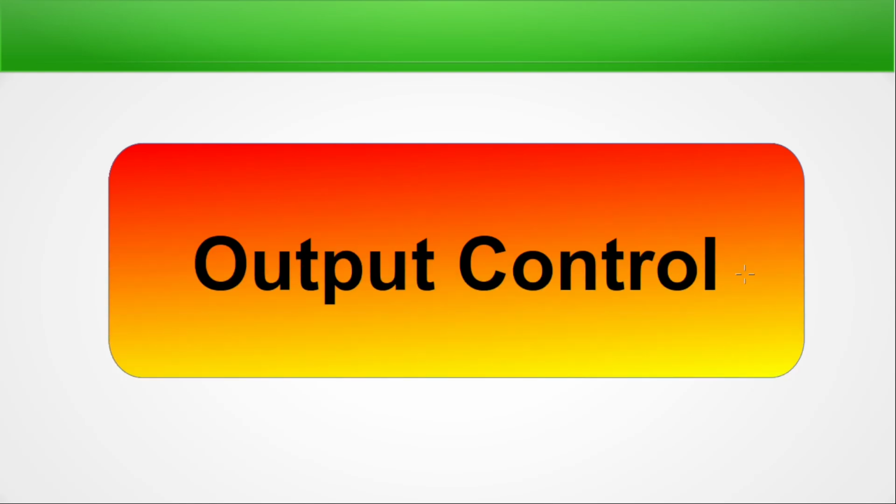Today's episode is focused on the output control of the SPICE. So this is the philosophy that we are going to cover in the entire episode today. So let us start with the print statement and example. So this is a simple print statement. We have a dot print, then we have a type, and then we have voltages.